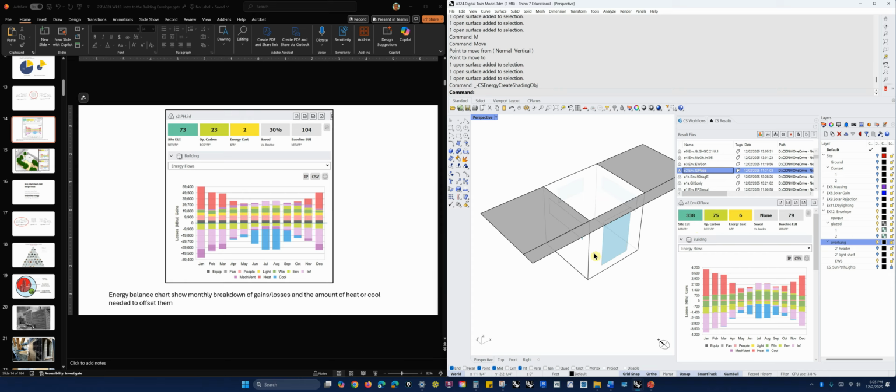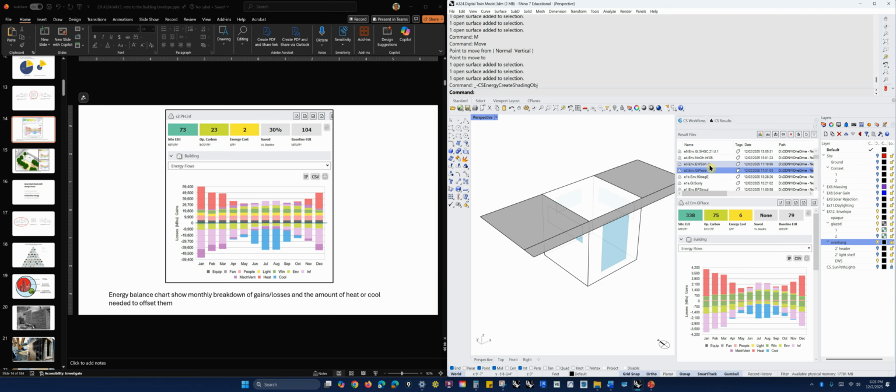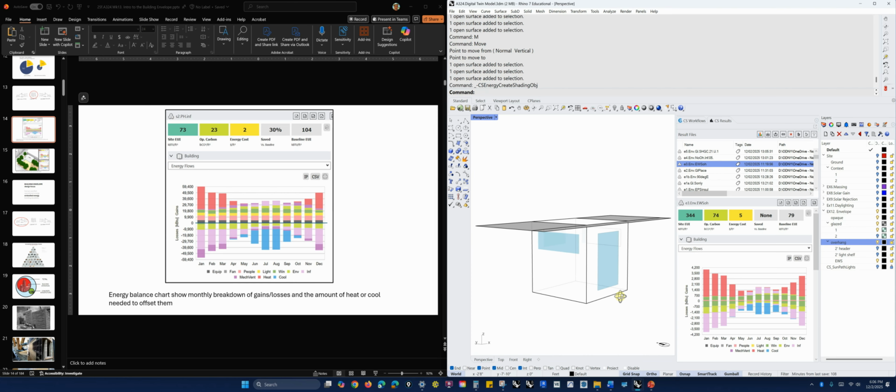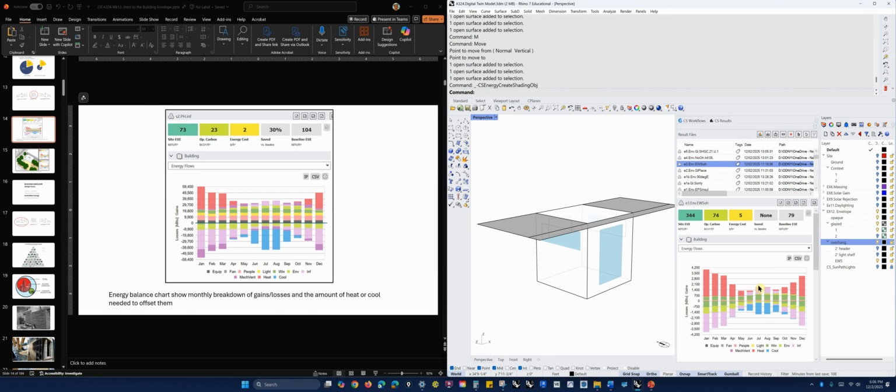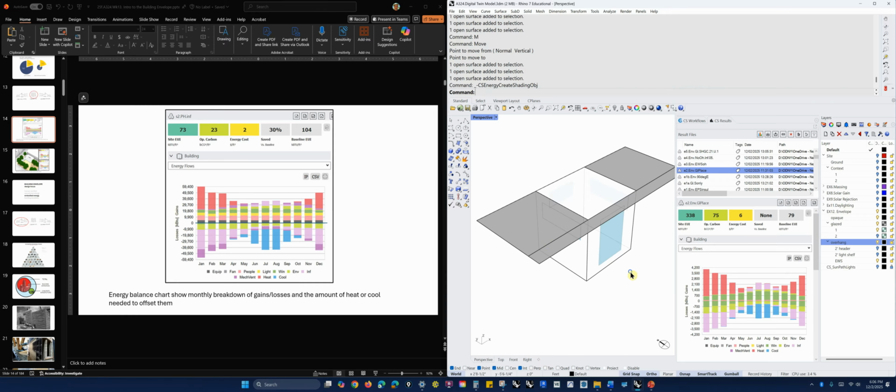And this is one reason why I am really pushing that early on, where you guys are, we start learning simulation, because the rule of thumb would tell me that this is better. And I'd be all proud of myself if I could even get these numbers without seeing this final. If I were trying to design this space and I was trying to drop my side UI and I saw this profile, I'd think, well, I'm going to get some shading here, and I'll look at the solar path, and I want a lot of shading on the east and west because that's really low.